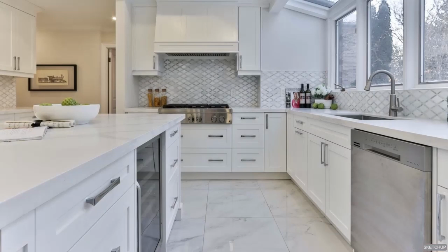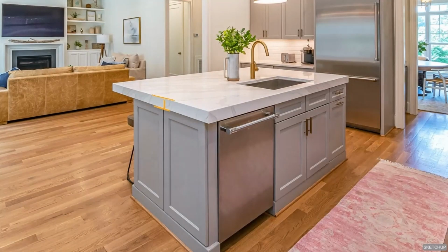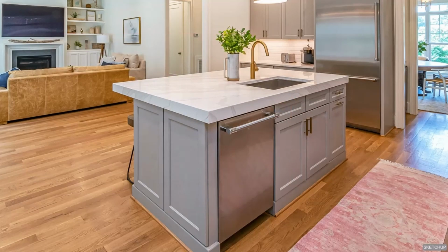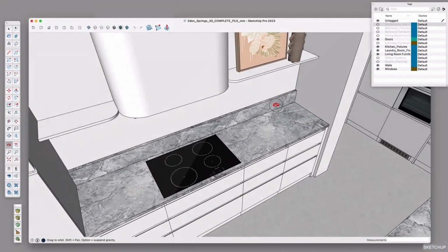When incorporating appliances, check their specifications to ensure they will actually fit within the cabinetry. For example, a 100mm thick benchtop from thinner porcelain material that was glued together may limit integrated dishwasher options due to the space deduction. Adjusting the benchtop height slightly is an option, but be cautious about exceeding 950mm, as this might feel uncomfortably high, especially for shorter individuals. Now let's dive into benchtop depths.